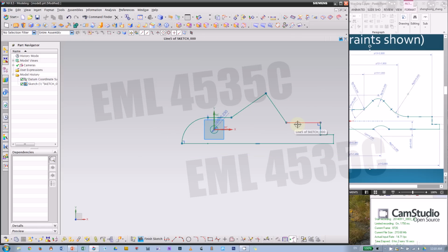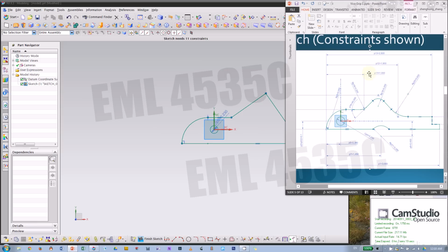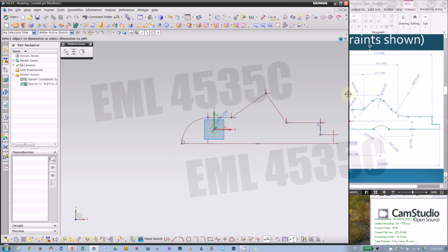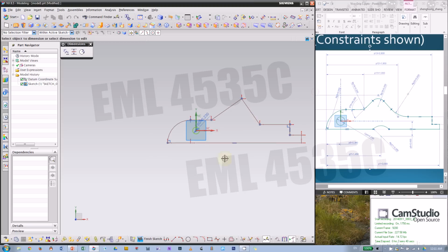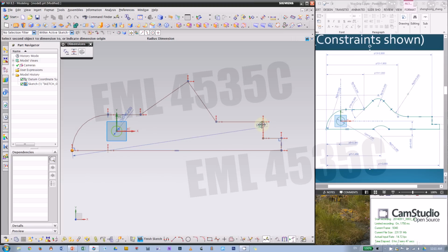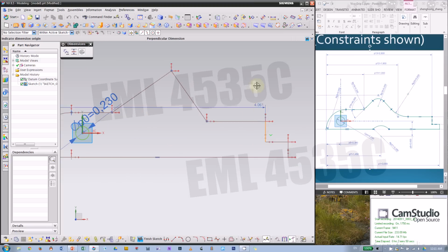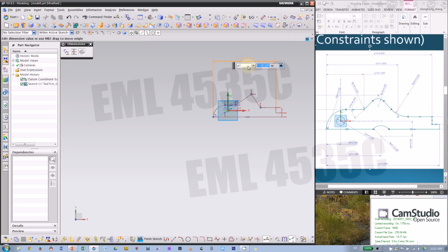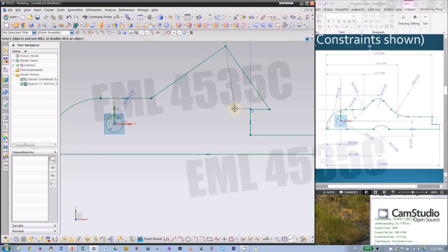Okay, now next we will add dimensions. Let's start from the top. P13, 12, and 11. Okay, and they all start from this rightmost corner. So I'll use invert dimension and make it a little bit smaller, from this corner to, let's say, this vertical line first. And that'll be 2.8. Okay, and don't worry about this here. We can just simply drag this back.